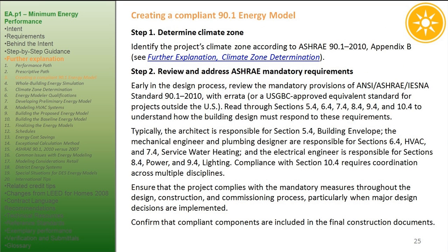Further explanation. Creating a compliant 90.1 energy model. Step 1. Determine climate zone. Identify the project's climate zone according to ASHRAE 90.1 2010, Appendix B. See further explanation, Climate Zone Determination.